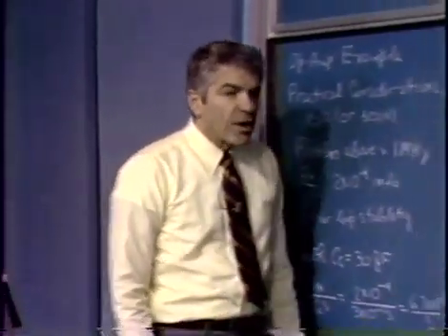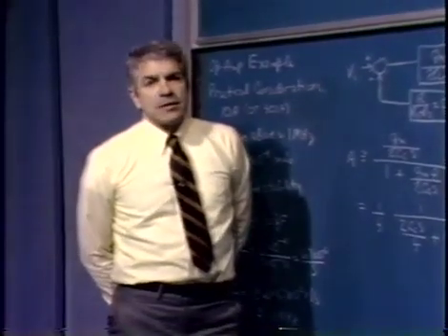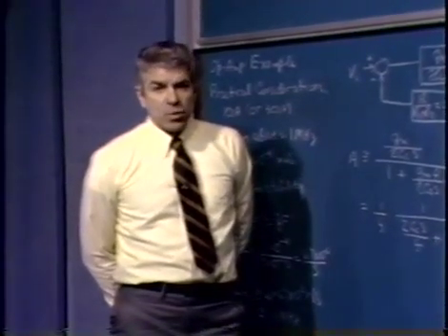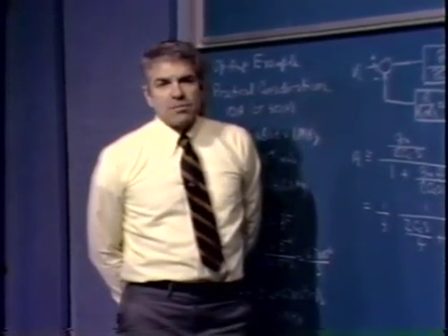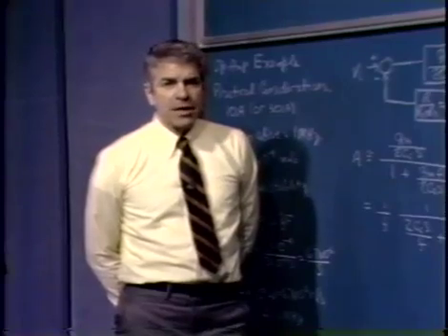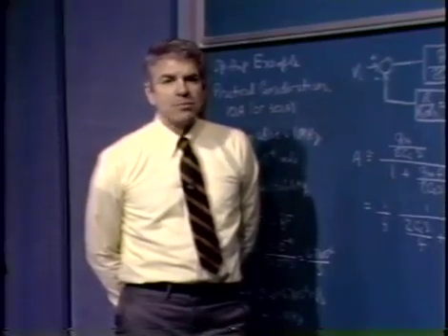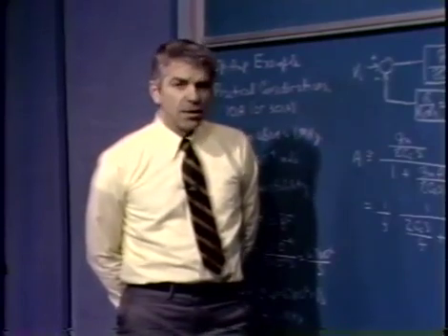Well, single pole compensation is a very good general purpose kind of compensation. It's the one that's normally used when fixed compensation amplifiers are sold. As I say, it can be certainly designed so that the amplifier is stable in a variety of feedback connections. It's only, or one of its problems, is simply that it's overly conservative in many applications, as we've seen.